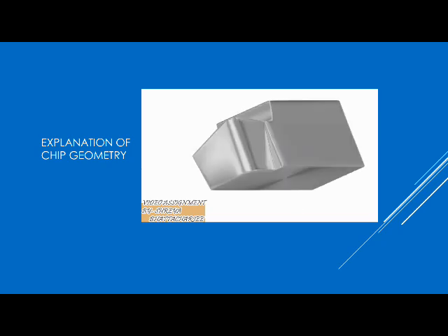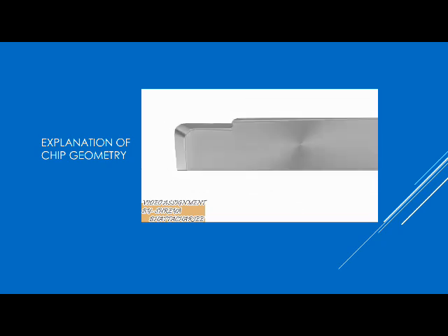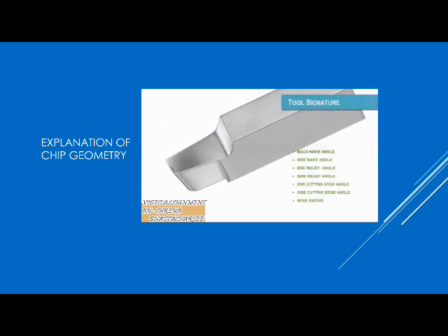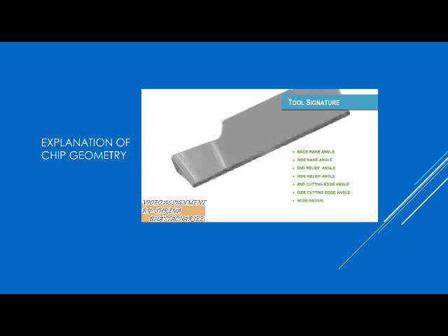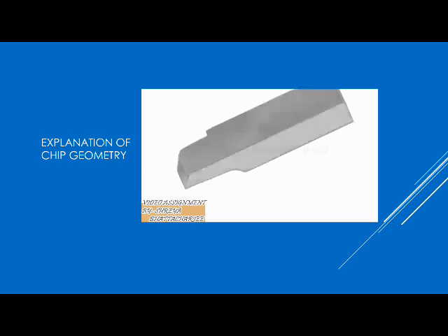Now let's have a look at the tool's initial position. You can see that the cutting edges form angles as shown. They are called the end and side cutting edge angles. These 7 parameters together completely define the geometry of a tool. We hope you now have a conceptual overview of cutting tool geometry.